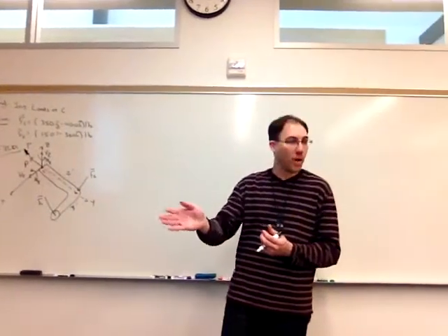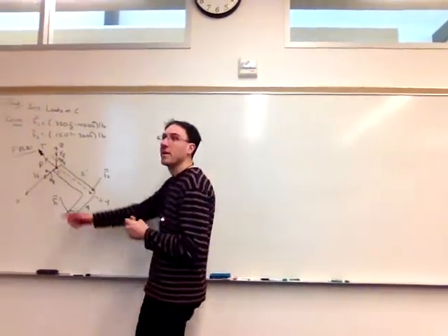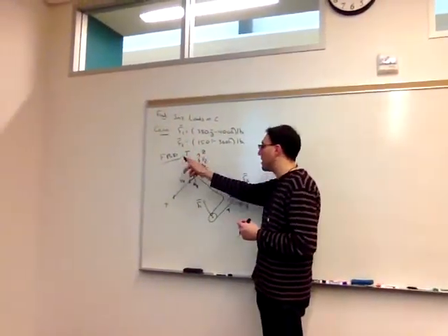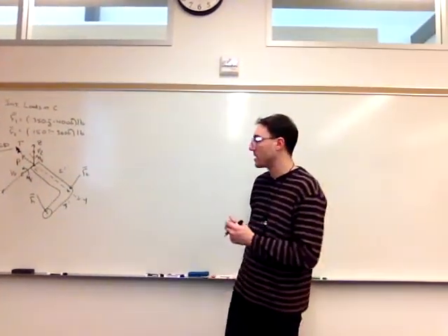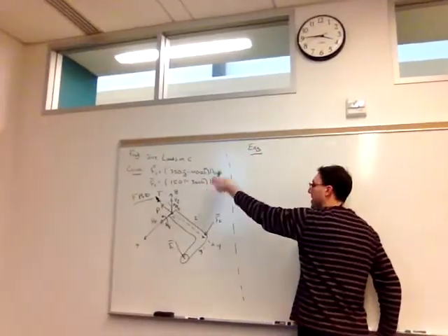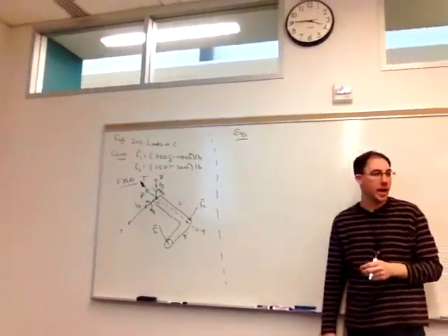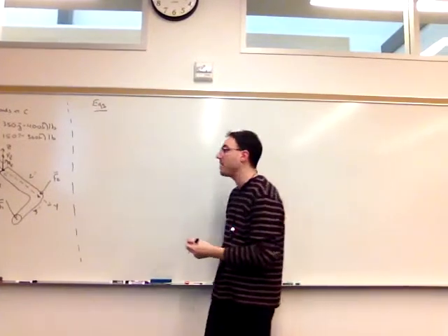However, you will need the wall reactions because you'll have the XYZ forces and the 3 moments at the wall that we don't see in this picture. At this point, it's just a 3D rigid body equilibrium problem like we saw in chapter 5.